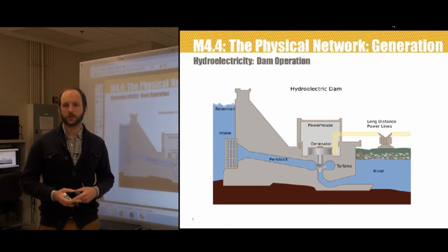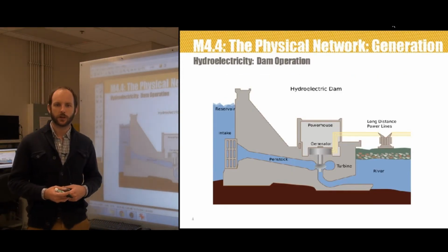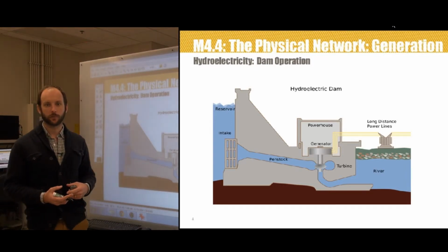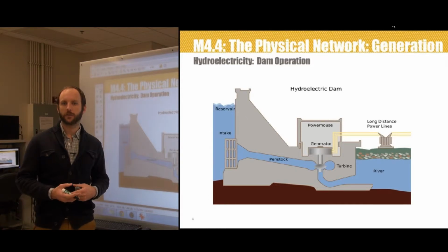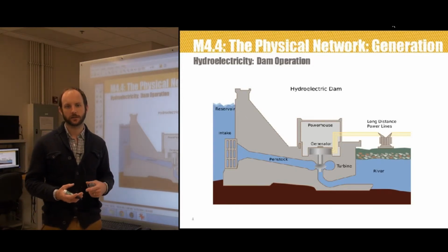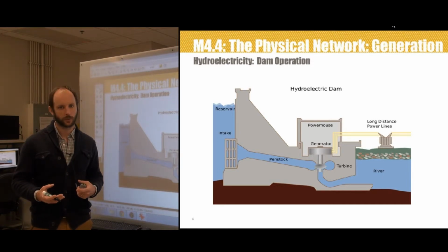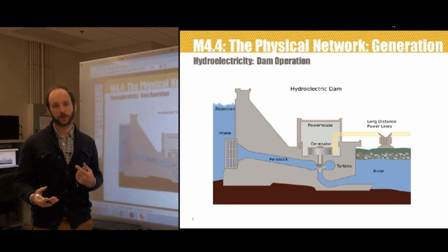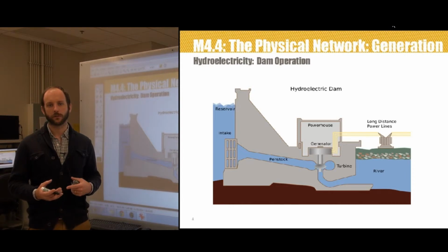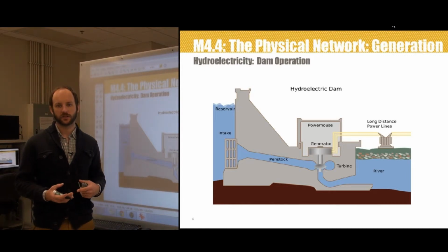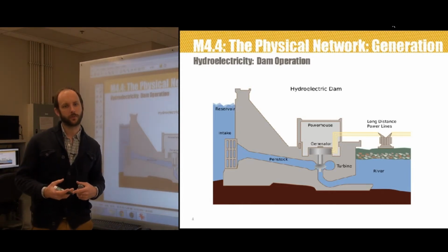Several different types of hydroelectric plants have been developed and are utilized to produce electricity. In the simplest form, a stream or river is diverted to pass through a hydraulic turbine. However, designs like this are highly susceptible to changes in water flow due to daily and seasonal variation in the water table. A construction of a dam can mostly mitigate these variations by creating a reservoir or storage pond. However, such designs can still be affected by long-term weather patterns.